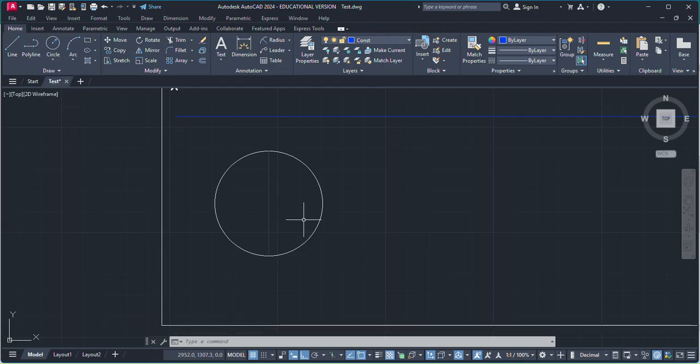Now to draw the projection of this, remember one thing: if you want to draw the projection of a circular profile, we cannot use lines. We are going to use spline fit for the curve surface, and to accurately track the points to create a circular profile, we need to divide this circular profile into more than these two parts.